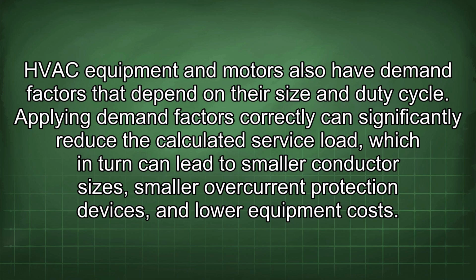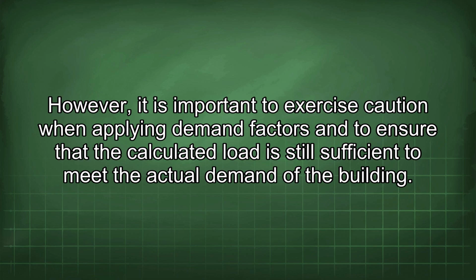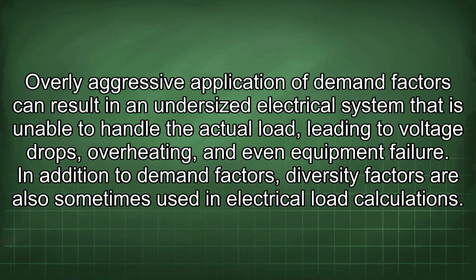Applying demand factors correctly can significantly reduce the calculated service load, which in turn can lead to smaller conductor sizes, smaller overcurrent protection devices, and lower equipment costs. However, it is important to exercise caution when applying demand factors and to ensure that the calculated load is still sufficient to meet the actual demand of the building. Overly aggressive application of demand factors can result in an undersized electrical system that is unable to handle the actual load, leading to voltage drops, overheating, and even equipment failure. In addition to demand factors, diversity factors are also sometimes used in electrical load calculations.